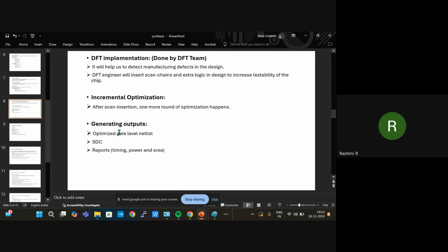In timing, we will check for 2 types of timing violations. The first one is setup and the second one is hold. Why will we not take care of hold here? Hold will be considered after the clock propagation only. So before place and throughout the synthesis, we will focus on setup timing and DRV optimization only.